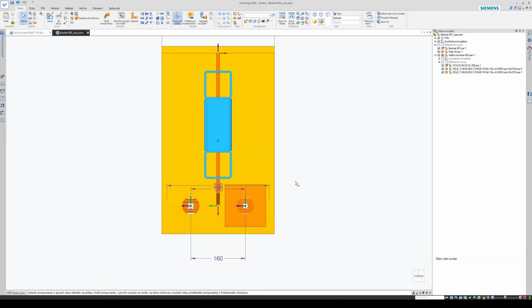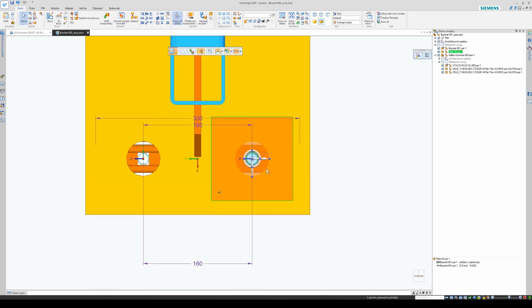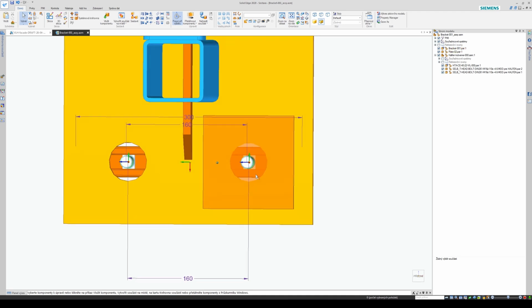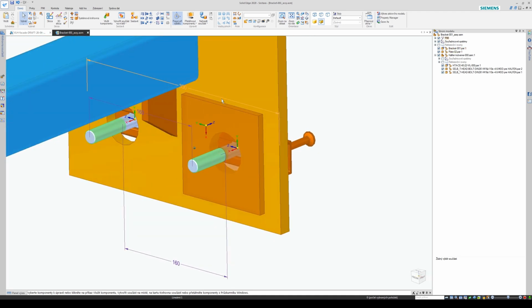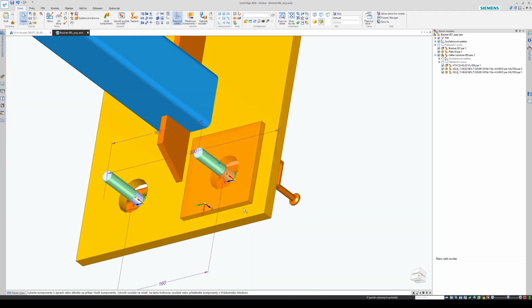Now, if I grab this one and look at it in this position, it's close, but it's okay. We can weld it here in these 3 places. It doesn't need to be welded all around when it's positioned. It's enough to weld it like here, here, or maybe here. It depends on the position.